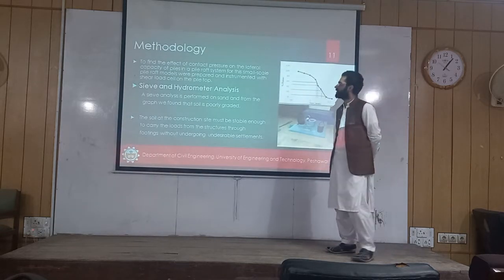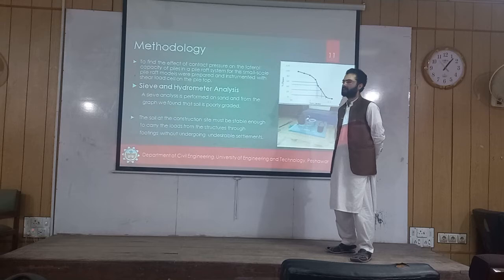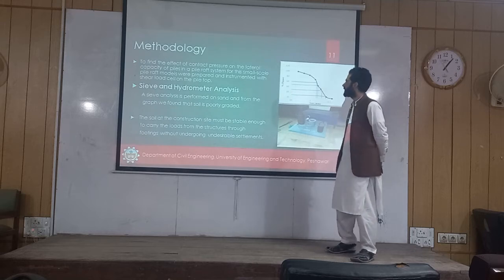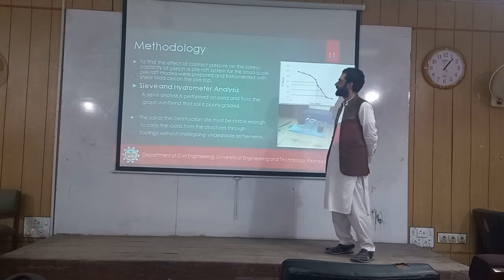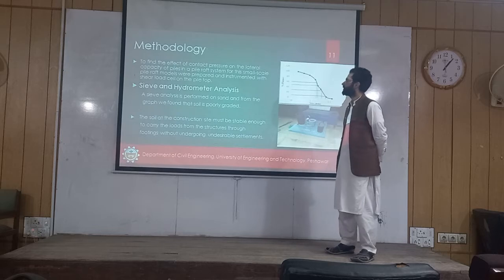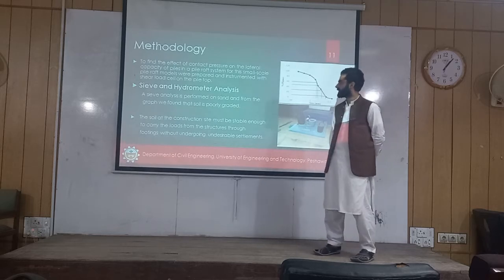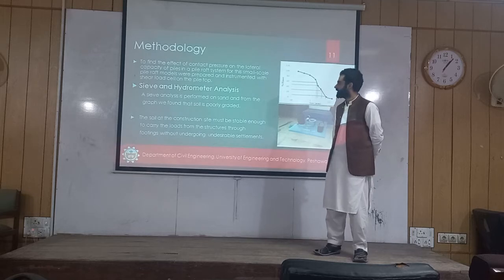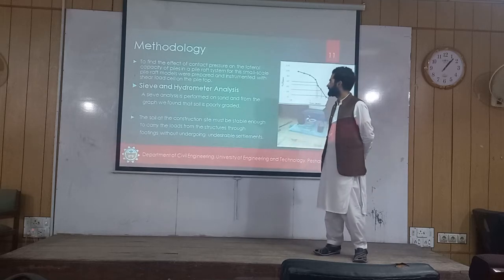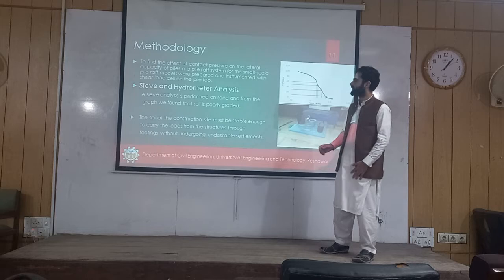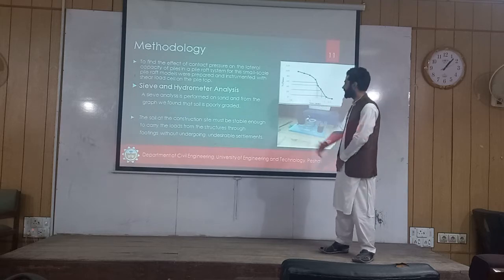Methodology: to find the effect of contact pressure on the lateral capacity of pile in a pile raft system, we use small scale pile raft models implemented with a shear load cell on the pile. We performed some tests like sieve analysis. Sieve analysis is performed on sand, and from the graph we found the sand is poorly graded. It is also shown here in the graph.